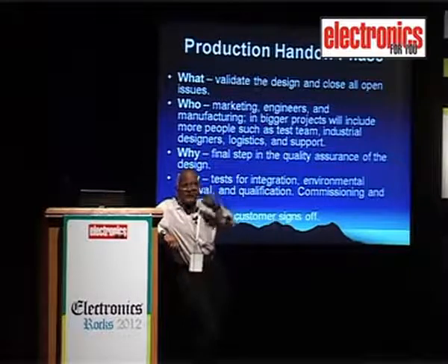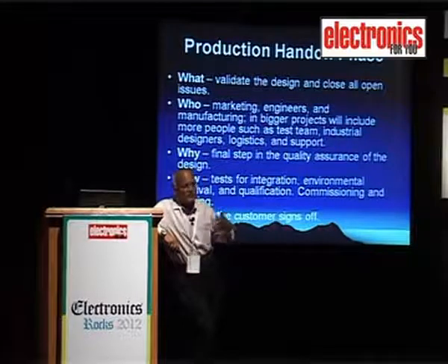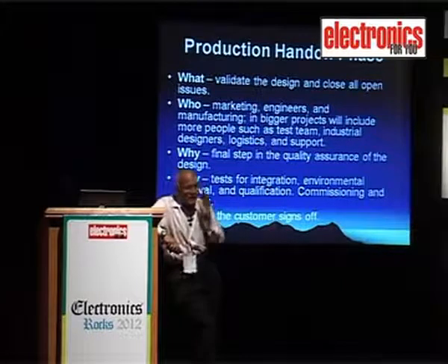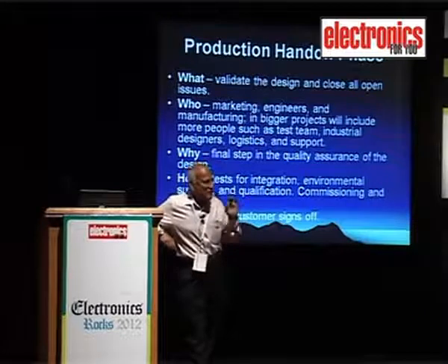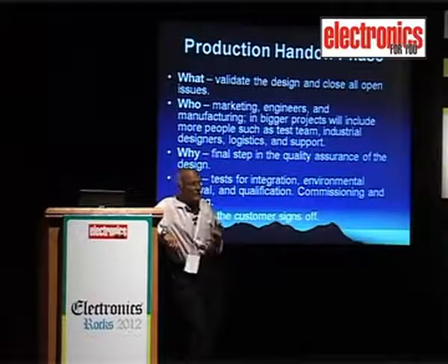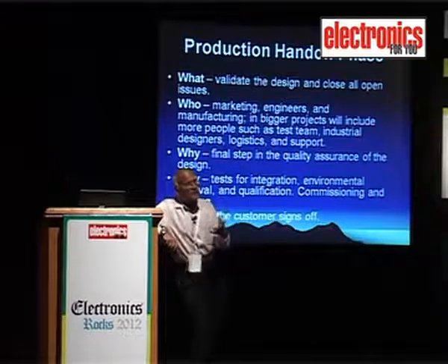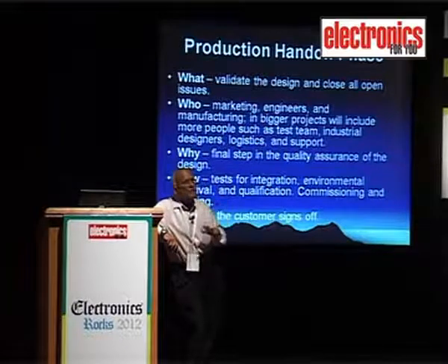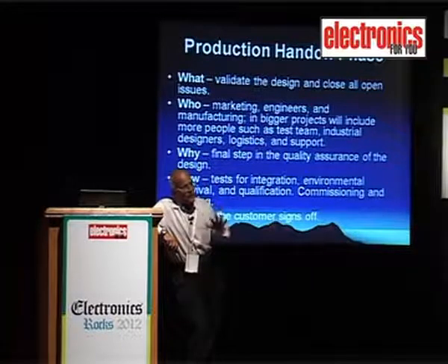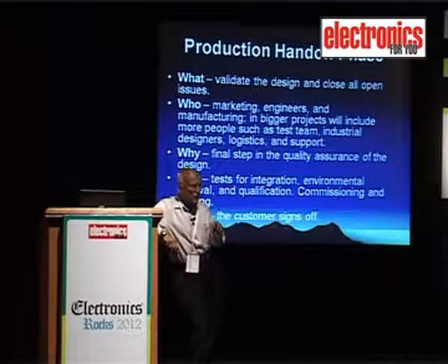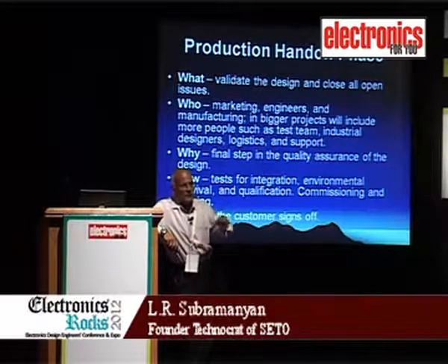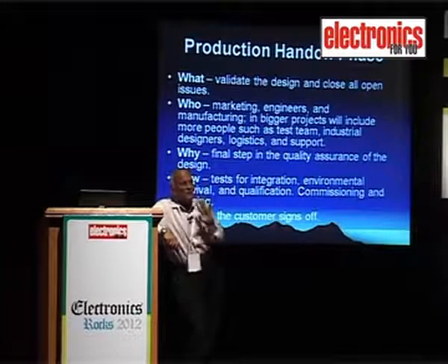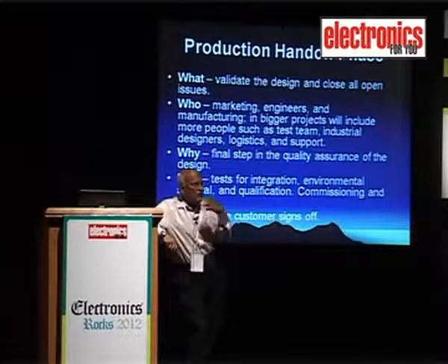And quite a few of those power supplies did not work the moment you put them on again. You don't get the same kind of response that you would otherwise have got from a power supply. Ripple should be less than 0.5%, the regulation should be X, Y, Z, and things of that kind. So you need to reform the electrolytic capacitors under the conditions of actual use. With a 240 volts AC power supply, you have to go back to zero, raise it to 240, keep it for some time, come back to zero, go back to 240, come back to zero. Then the power supply will work satisfactorily after 2 or 3 cycles, forming the films.